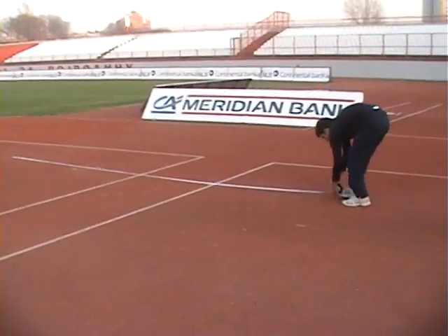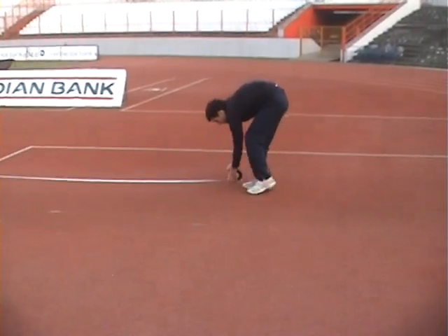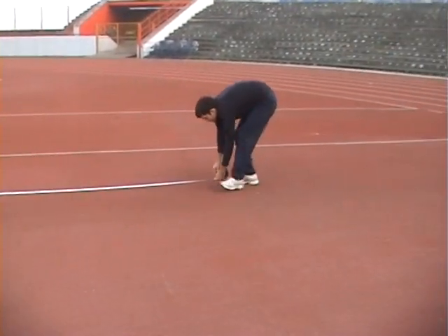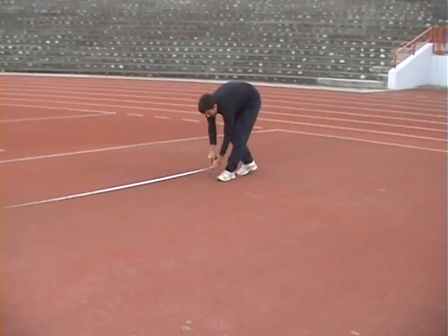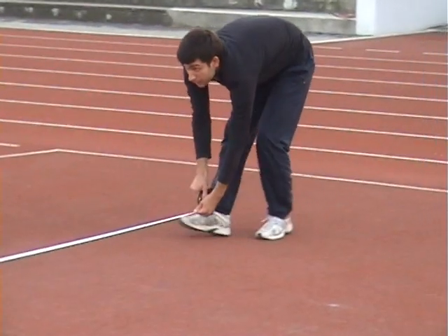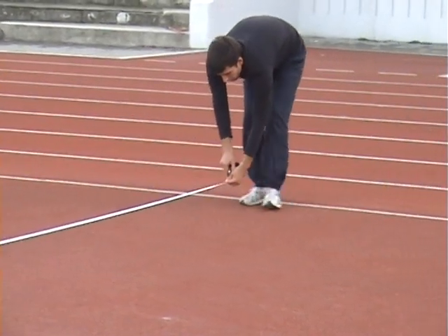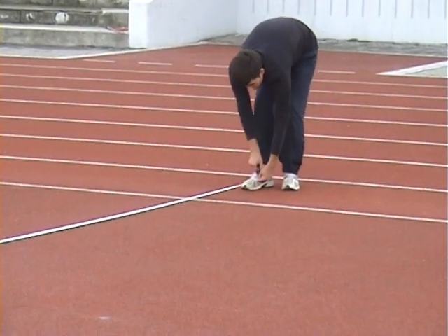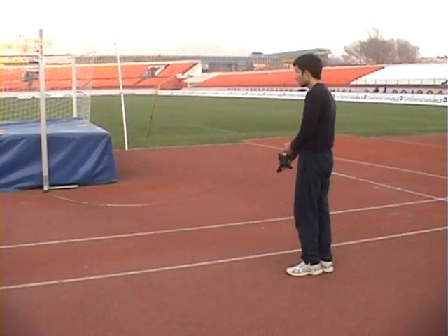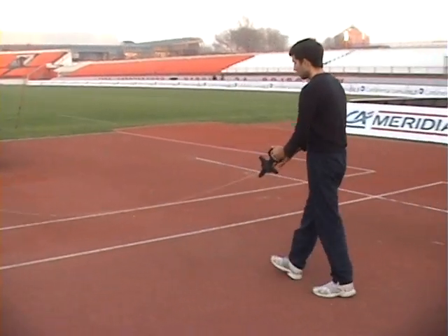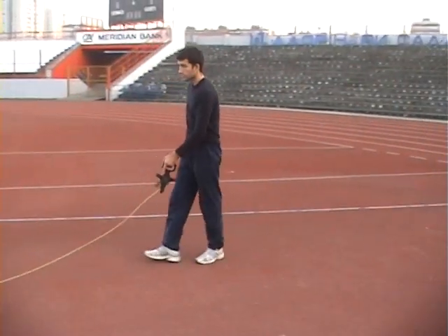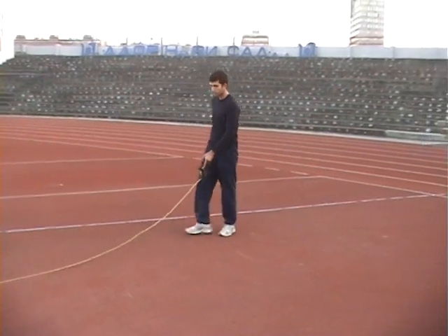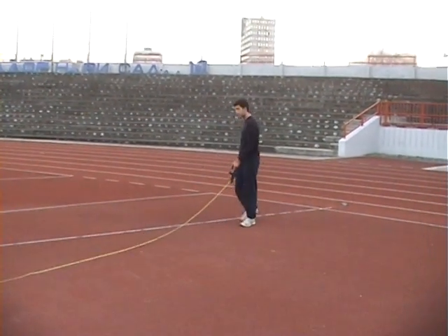The next step is to measure the length of the approach. At this point, certain problems may occur, since it's extremely difficult to set the length of the approach perpendicular at the right angle to the x-axis. Therefore, a second measuring tape is attached to the stand and stretched towards the specific value of the first measuring tape. The point where the values of the two tapes intersect is called the start point of the approach.